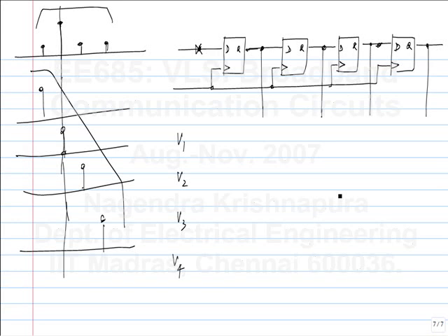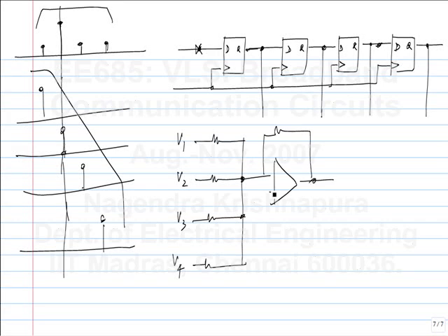I mean, to add voltages, you need to put things in series, which is more difficult than connecting all of them together, in which case you add currents. For instance, if you implemented this, this will implement a weighted summation of V1, V2, V3, V4. But this may not be how we implement the transmitter, but this is one way to implement it. So the classic weighted summation is implemented using an op-amp and 4 resistors.